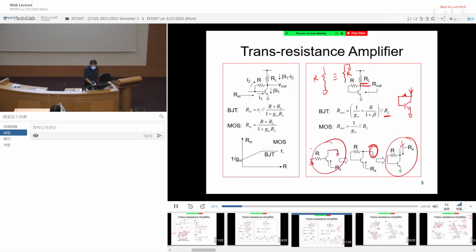But have we analyzed this guy? We did. If you look at the table, this is asking what is the driving point resistance looking up into the emitter terminal, where you have the collector terminal grounded and the base terminal connected to some resistor. And we derived the formula, which is this guy. Okay? So the driving point concept sometimes is not just straightforward. You have to be flexible and try to see that there is something equivalent. With this driving point concept, you can derive the output resistance quite easily.